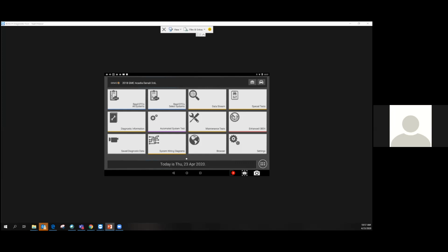Yep. So the dynamic is going to be like the one I showed you on that front-facing camera, where you drive the vehicle and it takes the surrounding objects, moving objects, and calibrates as you move. We have a very similar one on the same vehicle. There's one for the camera, which is optical. And then there's a separate calibration for the long-range radar for the adaptive cruise control, where it has a very similar drive cycle, but it is a little bit different, and it is a separate calibration.